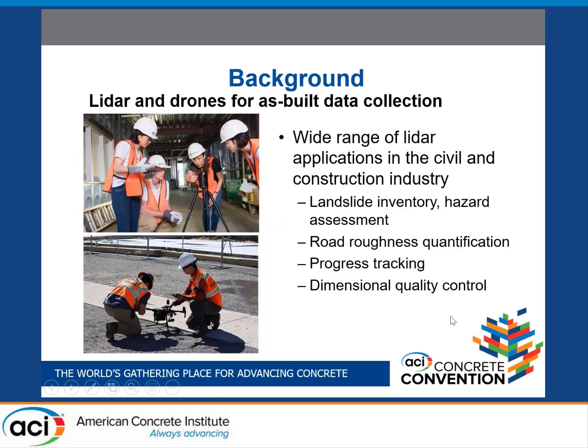Okay, so we wanted to see if we could leverage LiDAR and drones to collect the data and get the waviness information from that floor. For those who are not familiar with LiDAR and drones, LiDAR is also called laser scanners. They're basically high definition surveying equipment. The data you collect using LiDAR equipment is basically a three-dimensional point cloud, where each point is associated with XYZ coordinates, and if there is a camera, it is also associated with RGB color information as well.